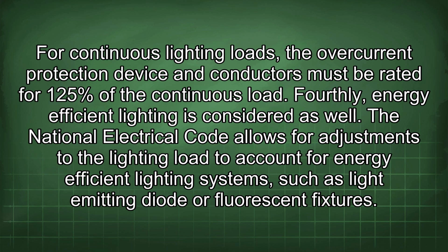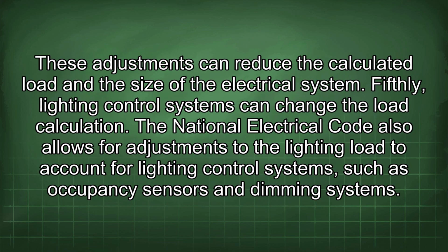Fourthly, energy-efficient lighting is considered as well. The National Electrical Code allows for adjustments to the lighting load to account for energy-efficient lighting systems such as light-emitting diode or fluorescent fixtures. These adjustments can reduce the calculated load and the size of the electrical system.